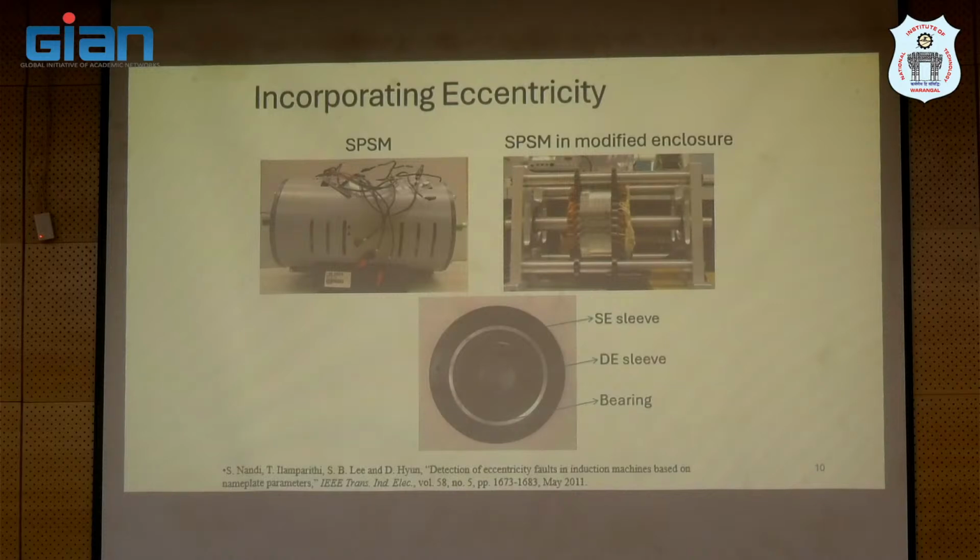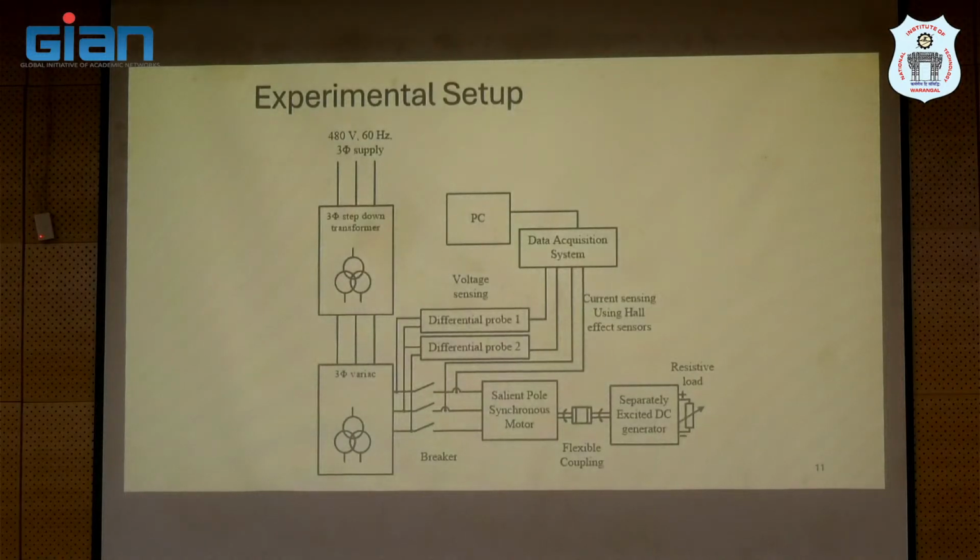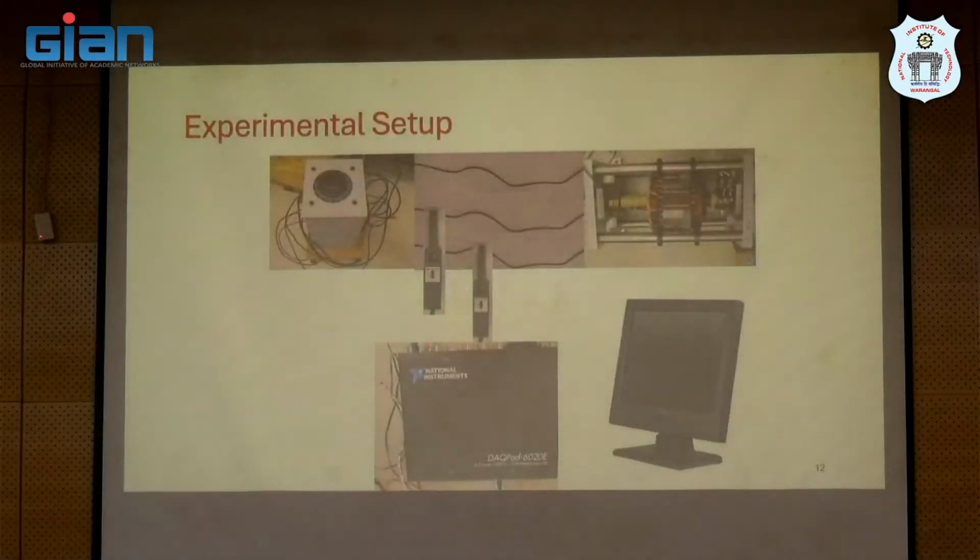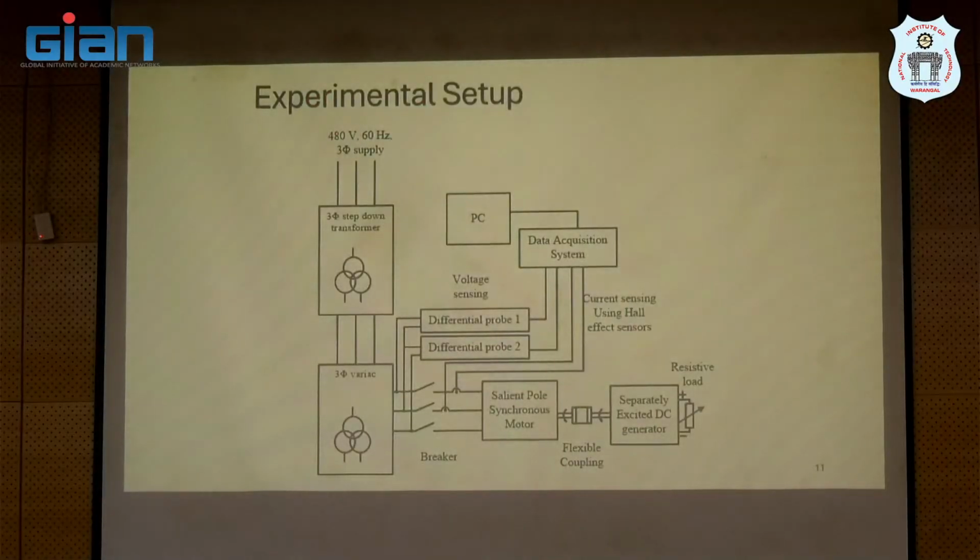So in a setup like this, protection is critical. The diagram does not show any protection, but that is not how it will be. You will have fast-acting circuit breakers along the lines. In a lab setting it's okay to skip some things, but it's better to have loss of excitation detection and appropriate protection for that as well. And then mechanical protection, wearing safety glasses just to protect your eyes. These are some mandatory procedural parts. Okay.